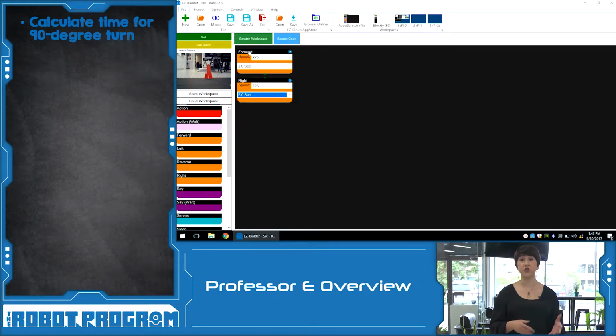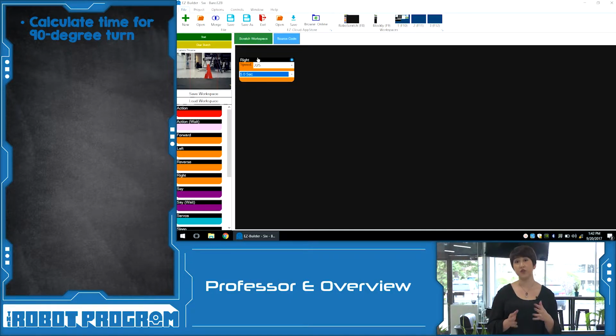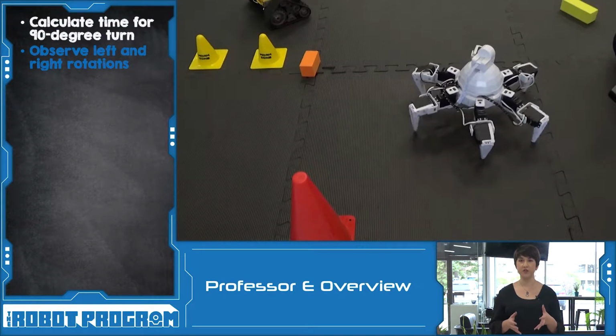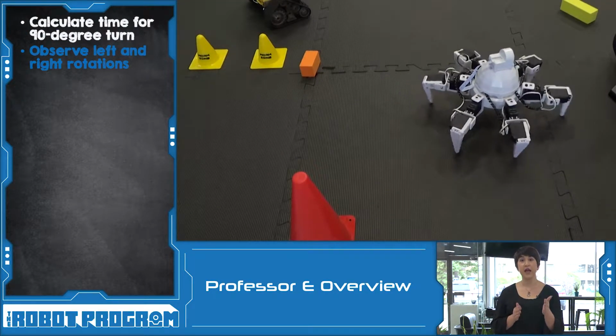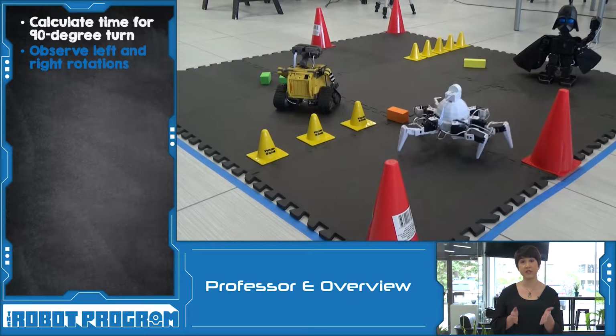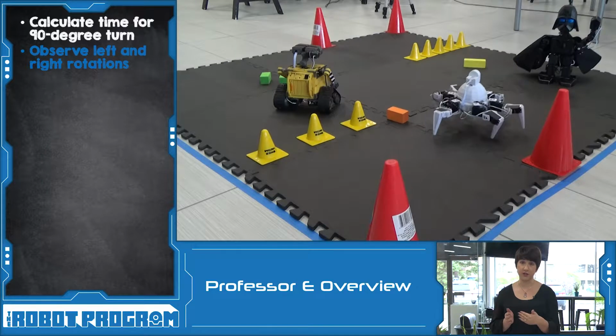Do the same thing for turning right or left. Using the speed that you want, again, I chose around 225, test how long it takes your robot to do a 90-degree turn. This way, if an obstacle is facing your robot head-on and you need to do a complete 90-degree turn around it, you'll know exactly how long it takes your robot to move those 90 degrees.